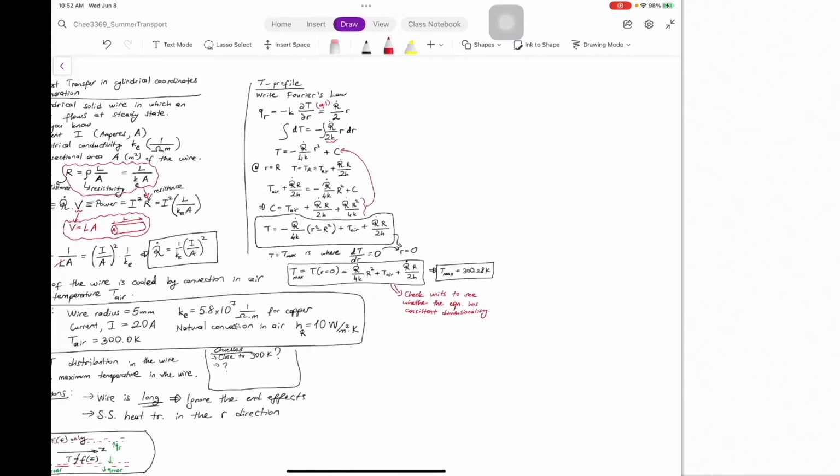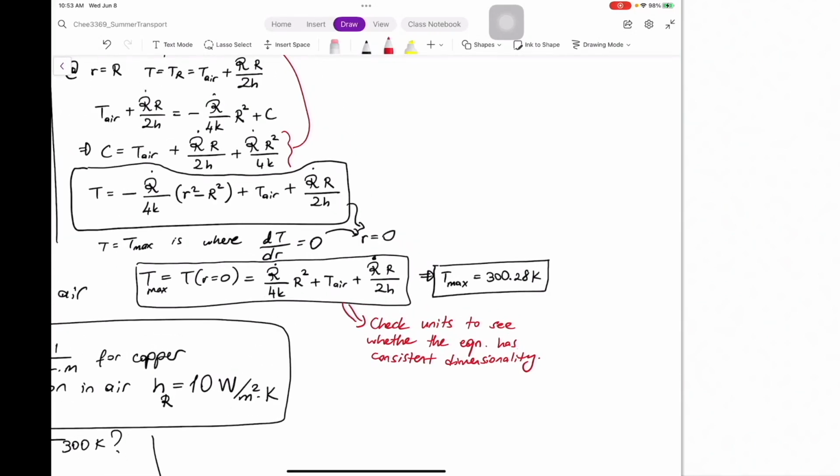You can also do different special cases. For example, you can set the heat generation to 0 to see how the temperature profile would look without any heat generation, and you can check your answer against the solution for a temperature profile without any heat generation. Okay, good.